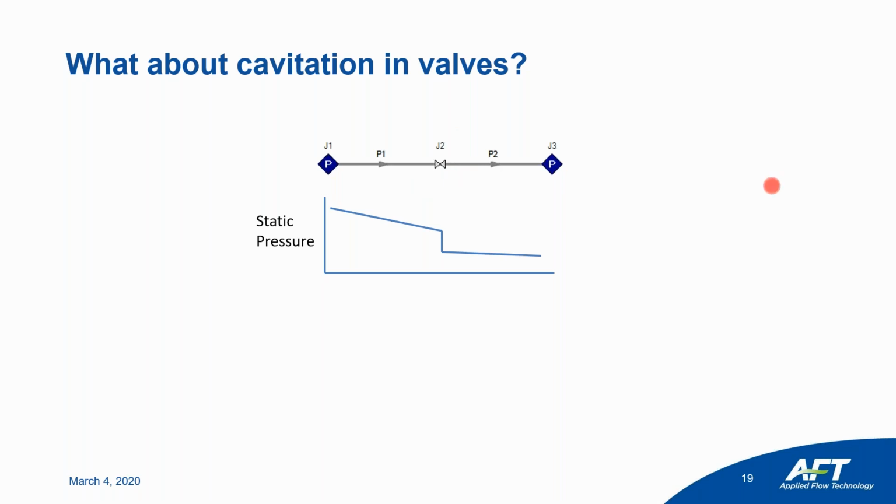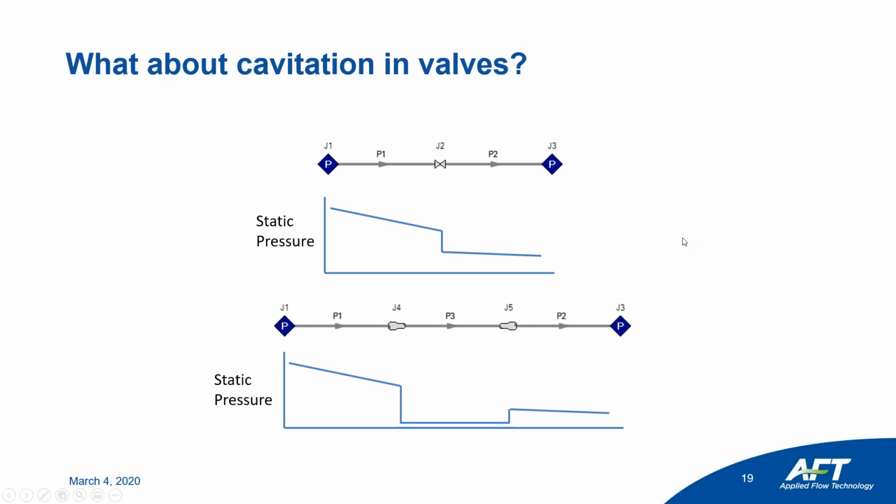So not only is it reducing the pressure, a drop in stagnation, you're also going to see a contraction. If you imagine the valve as a very small hole that all of that flow has to pass through, we're going to see our static pressure drop. This comes from the balance of stagnation pressure equaling your static pressure plus your dynamic pressure. So as your velocity goes up, your dynamic pressure goes up. As a consequence, that static pressure has to drop. And so it may even drop to the point that it's going below the vapor pressure and causing cavitation.